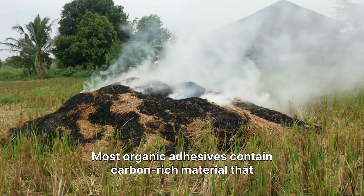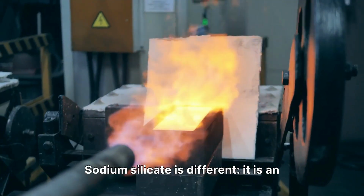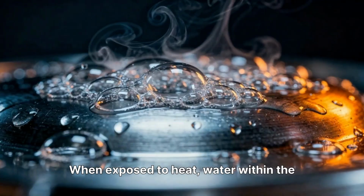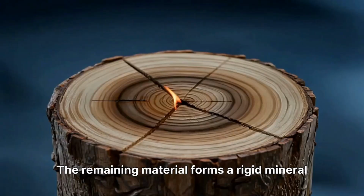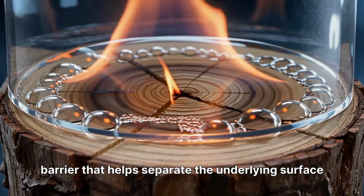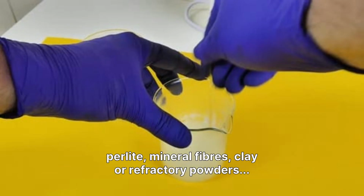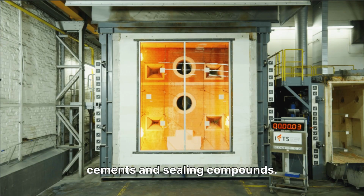Most organic adhesives contain carbon-rich material that can burn or produce smoke. Sodium silicate is different. It is an inorganic mineral binder and does not act as fuel. When exposed to heat, water within the silicate absorbs energy as it evaporates. The remaining material forms a rigid mineral barrier that helps separate the underlying surface from heat, flame, and oxygen. Sodium silicate is commonly combined with vermiculite, perlite, mineral fibers, clay, or refractory powders to manufacture fire-resistant boards, doors, insulation, coatings, cements, and sealing compounds.